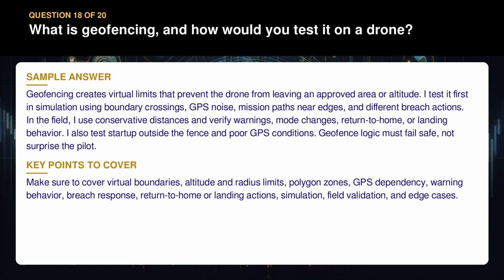Geofence logic must fail safe, not surprise the pilot. Make sure to cover virtual boundaries, altitude and radius limits, polygon zones, GPS dependency, warning behavior, breach response, return to home or landing actions, simulation, field validation, and edge cases.